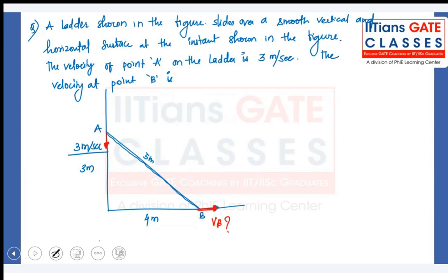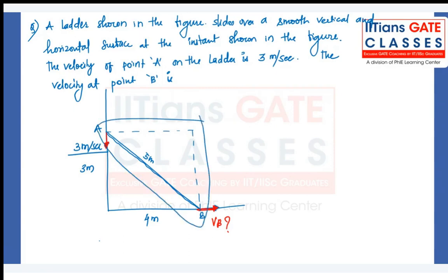See, what is assumed here is, if you draw the dotted line, you can assume this as one single link, and this link is rotating about this instantaneous center of rotation. If you draw the perpendicular to the velocities, wherever it cuts, this is the point, so you can call it IAB, the instantaneous center of points A and B. What is instantaneous center? The center with respect to which the whole body is assumed to be rotated,